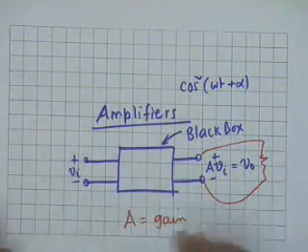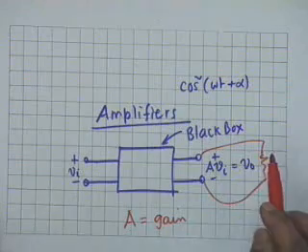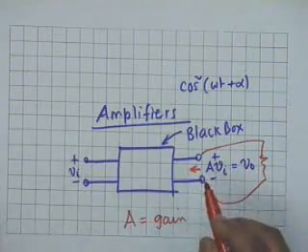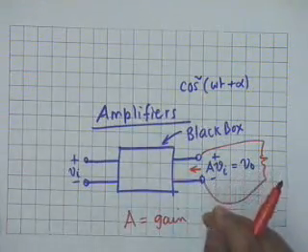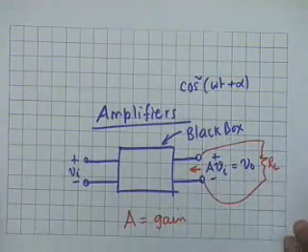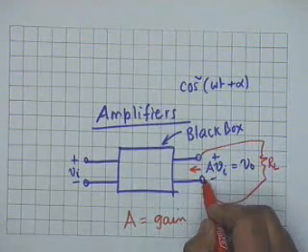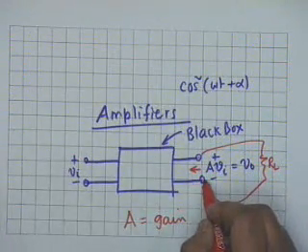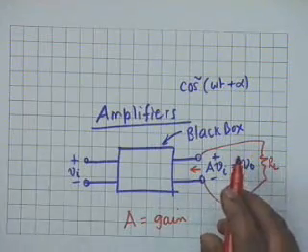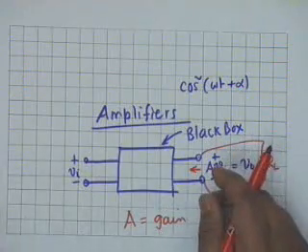Now this, irrespective of what is connected here, implies that the Thevenin equivalent resistance looking here shall be equal to, if the voltage developed here is AVI, irrespective of the value of RL, what does it imply with regard to the Thevenin equivalent resistance looking back from these two terminals? 0. That is correct. So this is one of the implications of an ideal amplifier, that the output resistance, this Thevenin equivalent resistance, is called the output resistance. So the output resistance shall be equal to 0.